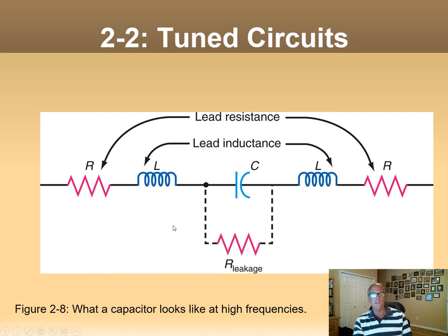So capacitors, actually, with leads, we have inductance, we have a little bit of resistance in there. So they're complex devices. We usually ignore everything except for the capacitor, except for at really high frequencies. Then all this stuff comes into play. That's why surface mount capacitors are often used, very small, no leads on them, which removes most of the inductance. Depending on the dielectric of the capacitor, we might have some leakage resistance though still. And obviously the more expensive capacitors have less leakage.